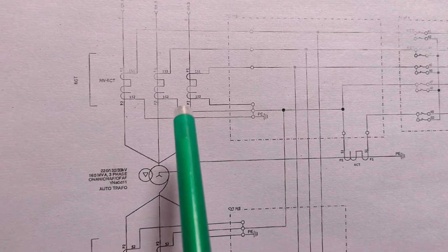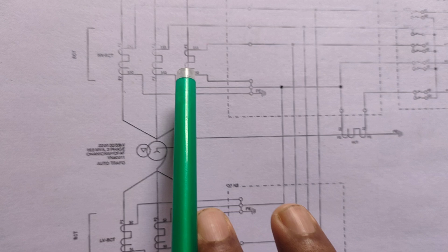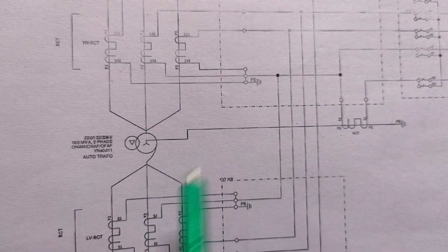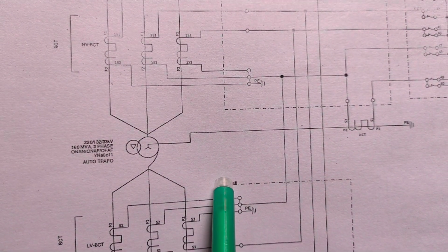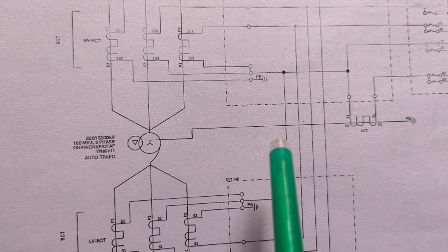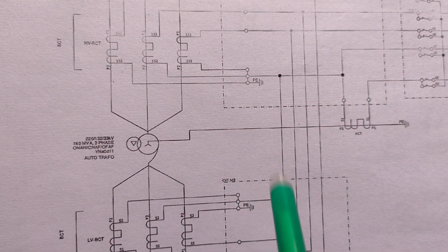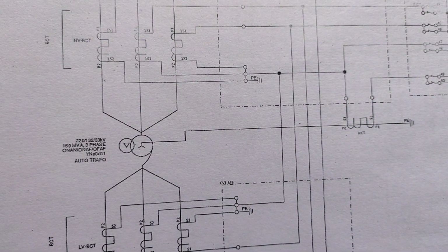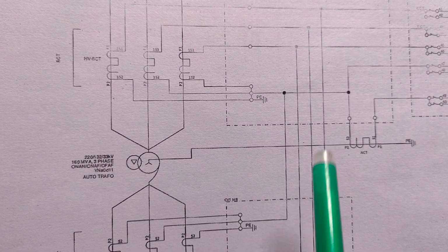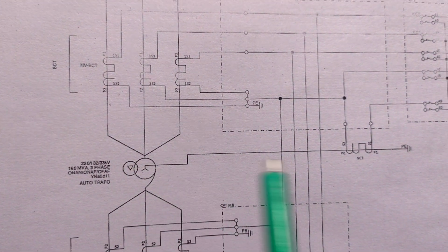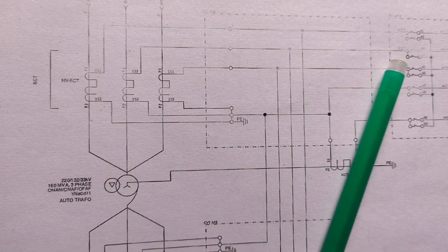So REF protection is the restricted earth fault protection in between the transformer's primary winding and secondary winding, starting from the HV bushing to the LV bushing to the neutral bushing. This zone is restricted. If any minor or incipient faults are developing inside the transformer, or any core damage or insulation problems or anything else inside the transformer, this relay will operate, and accordingly the transformer will be taken out from the source, because this REF protection is connected with the breaker trip coil.